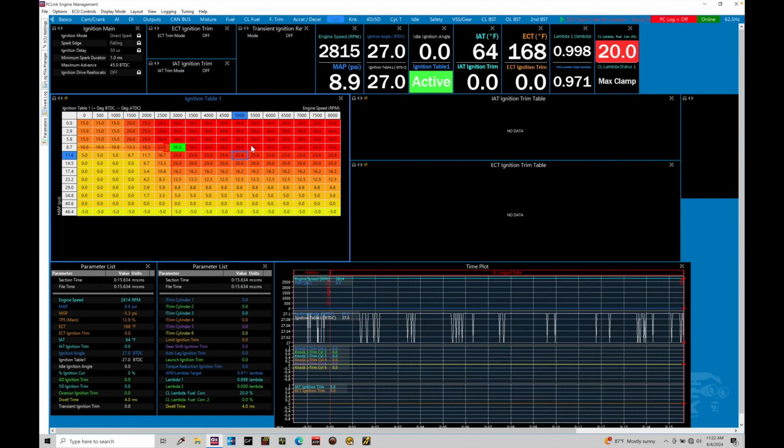Now, with this, a couple things that we're assuming if we're not running any ignition modifier tables. This main spark timing table assumes that the engine is warm, so we're up to about 160 to 190 degrees Fahrenheit. That's typical average coolant operating temperature for most internal combustion engines. It's also going to assume average inlet air temperatures. So we have our intake air temp sensor reading, not to be confused with charge temperature. We know they're different, but the intake air temperature reading is about maybe 60 to 70 degrees Fahrenheit. This table assumes we're in those kind of average running conditions.